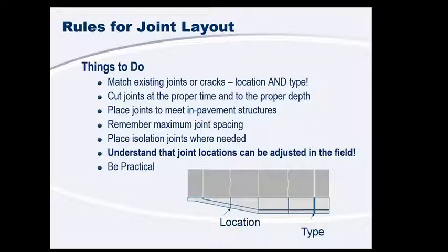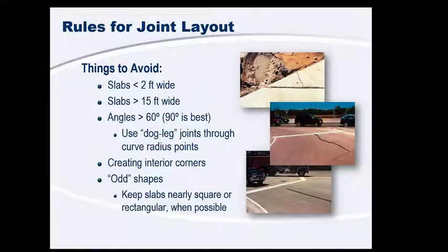One big thing for agencies and engineers to remember is that what's in the field may not be exactly what's on the plans. And that means that the contractor has to adjust to what he sees in the field. So the contractor really needs some leniency to be able to adapt to what's out there. Additionally, if you get a contractor involved in the early stages of the joint layout, you'll probably get some good feedback on what's practical and what should be done which way.